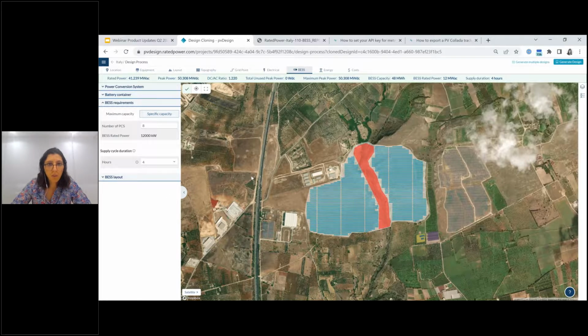Another question, how can I change the position of the substation? If you mean by that change in the position of the equipment, it is unfortunately not possible to do that manually for the moment. But if you want to just change the position of the whole substation, you can just change the ST polygon in the KML and upload it again to the software.